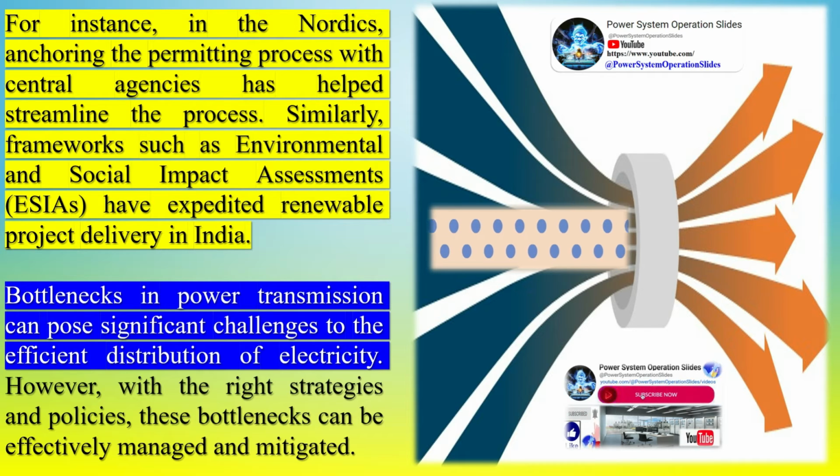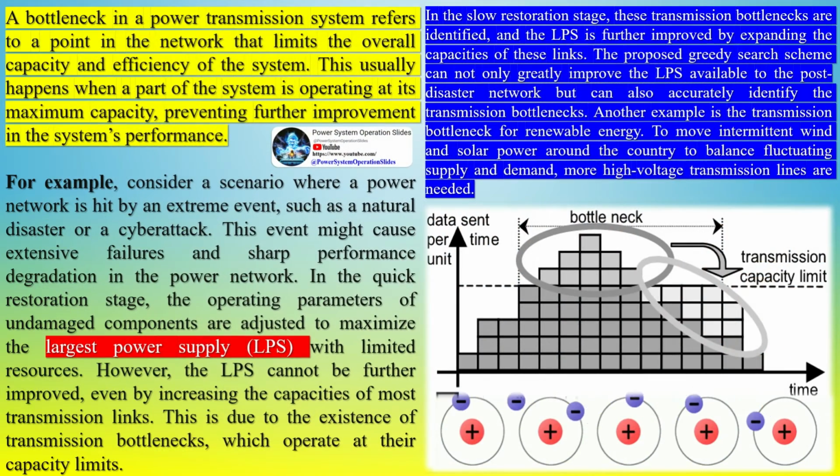Enhanced reliability. Microgrids offer increased reliability compared to large-scale grids. When the main grid fails, a microgrid controller detects the disruption, disconnects from the utility, and activates island mode. In island mode, the microgrid continues to supply power to critical loads using its local resources. Once the utility service is restored, the microgrid reconnects to the main grid.